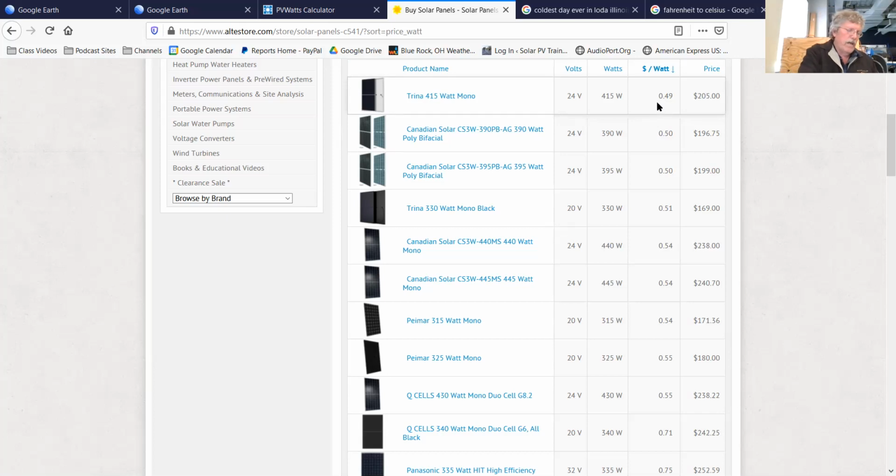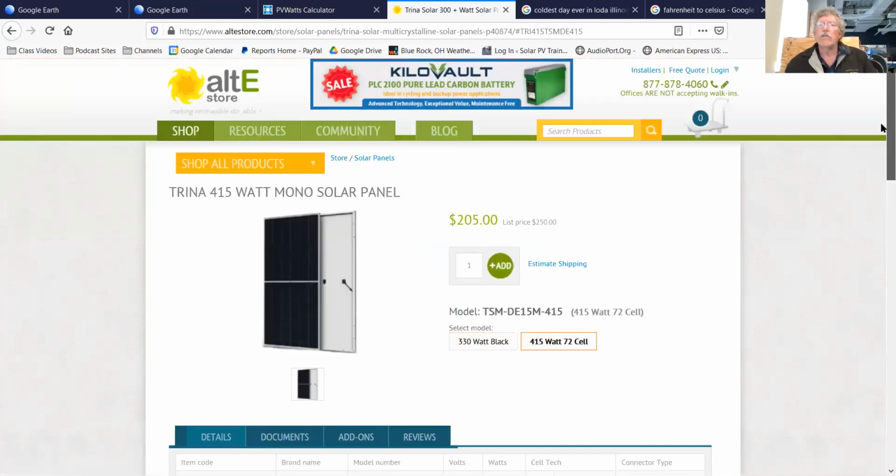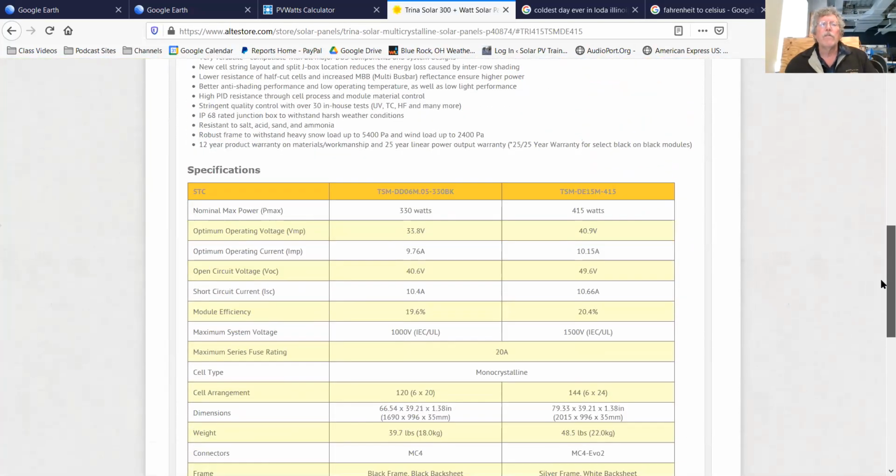I'll go with the Trina, and I'm going to make some notes here. Trina, it's 415 watts. And we're going to need to know some of the specification details on the Trina solar panel. Some of them are very easy to find. I'm just going to write down the VMP is 40.9 volts. The VOC is 49.6 volts.